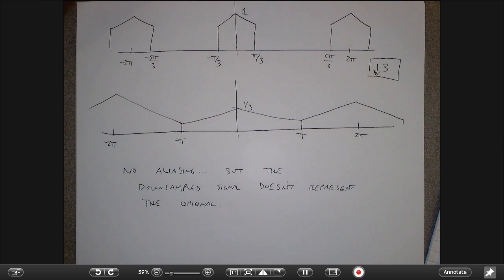I mean, you can't really have it. If you know the high frequency information is important, but you also know that your sampling rate is below the Nyquist rate to capture it, then you're kind of stuck, right? You're going to lose that information either via aliasing or via low-pass filtering with the pre-filter. You can't have it both ways. If you know that you need that stuff, then you need to be sampling fast enough to get it, is what it comes down to.